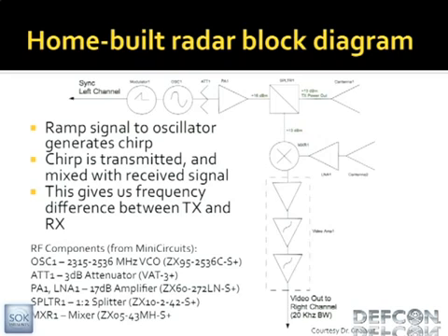And then there's this thing down here called a video amplifier, and what that does is it takes that really small signal, that's still pretty small, and amplifies it a bunch of times at low frequency so we can feed it out to the computer. And there are 2 outputs to this. One of these is the sync pulse, which basically tells us when the chirp starts, and the other one is the actual data signal back out.